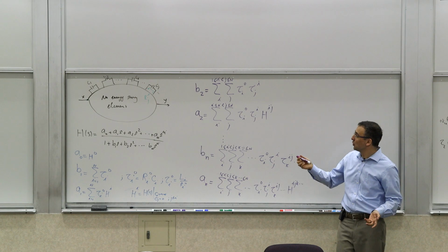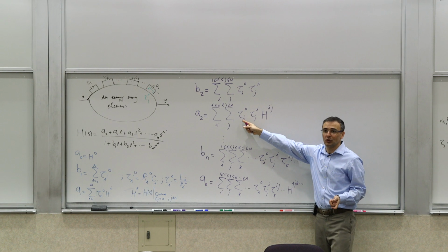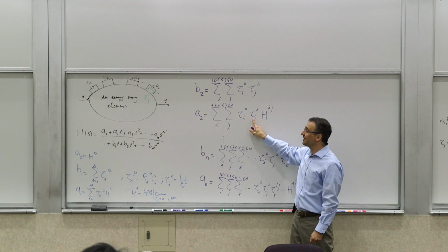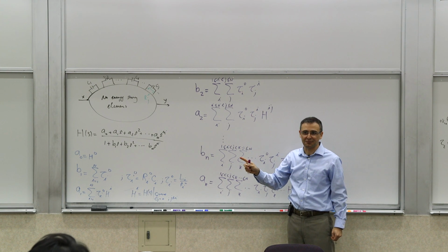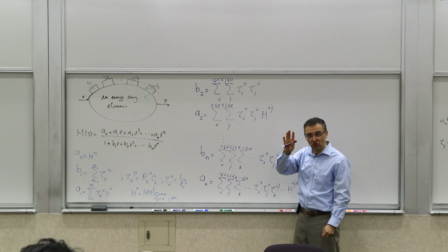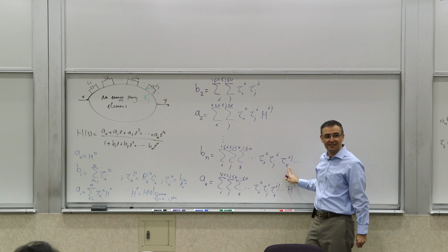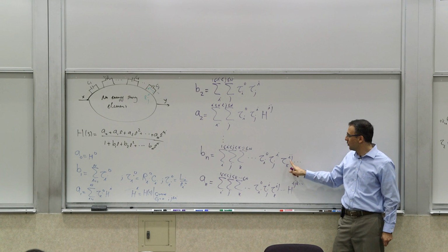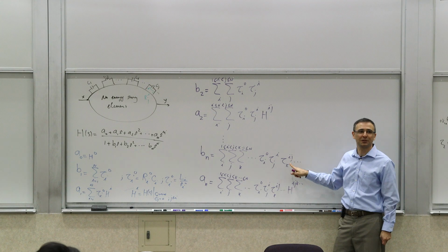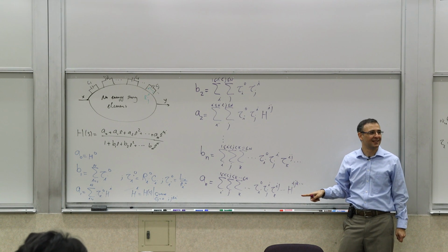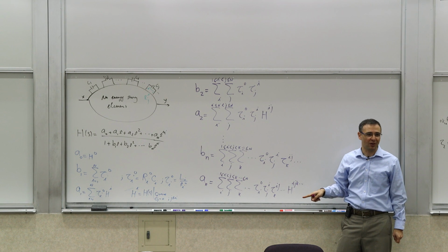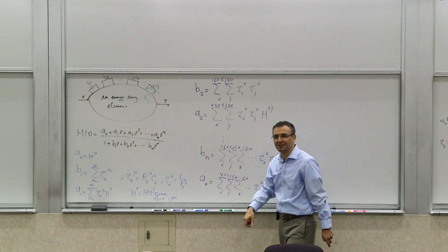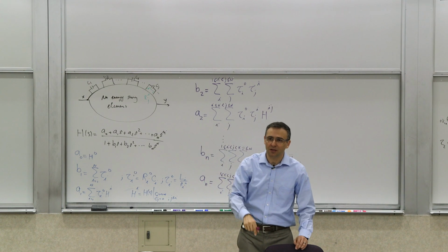So actually you don't need to calculate all of them, because it's not that you need every combination, you just need a few. And sometimes certain reindexing makes it easier to calculate some of these things. Because in general, the higher order of these things are actually easier to calculate. You can imagine why. There are more capacitors that are short-circuited, so those time constants become almost trivial. You look at, well, this is short, this is short, this is short. There's one resistor sitting here, right? That's it. But let me show you examples of that.